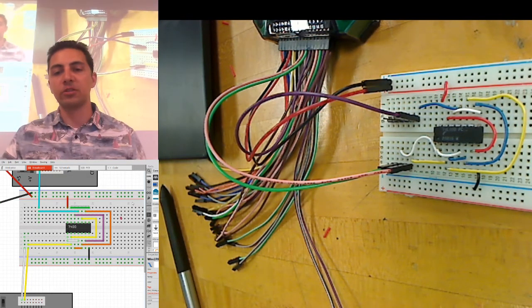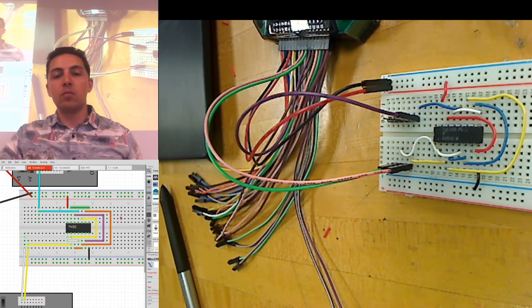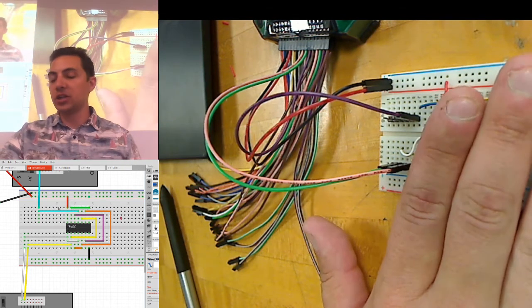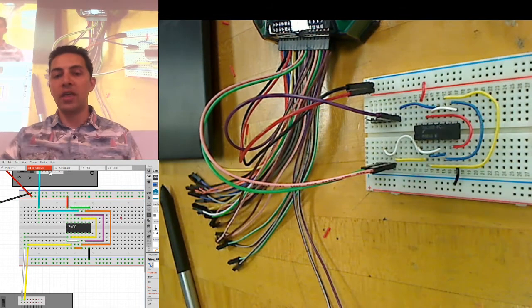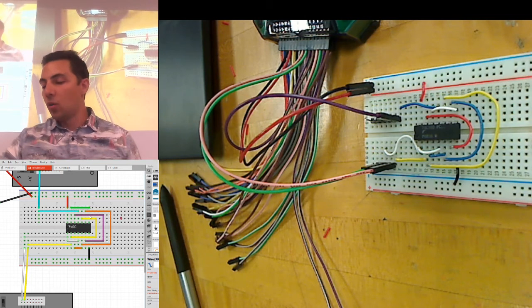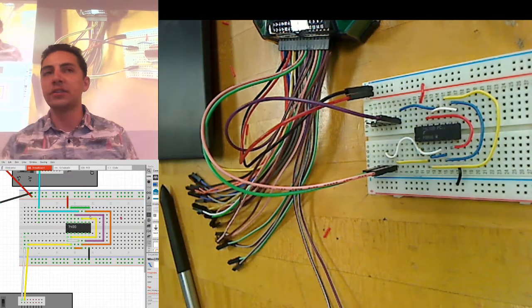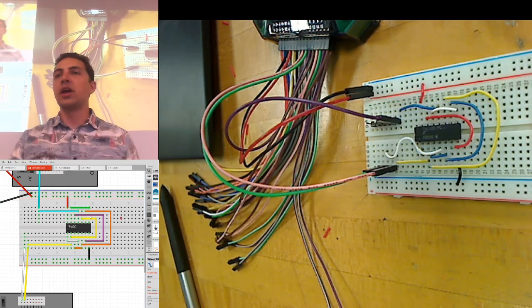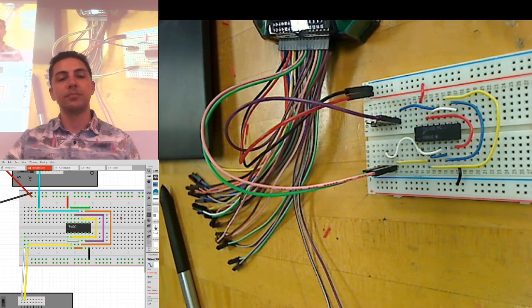We talked about the power supply. One of the things I want to really stress is never make any changes, either with the tool or on the circuit itself, with the power on. Before you do anything, turn the power off. Why should you do that? Because if you accidentally, while you're unplugging this wire, touch it to another wire, you've created an electrical short. Shorts are never good. You don't want those. You let the magic smoke out. So always turn the power off.